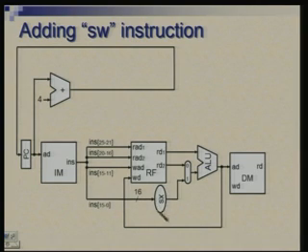So, this is the block which is doing sign extension. It takes 16 bits as input, bit number 0 to 15 of the instruction, and it does sign extension. Okay. So, here it is a 32 bit output. So, wherever I have not labeled things, assume that you have 32 bit output, 32 bit signals. Okay. Each wire is actually carrying 32 bits. Exceptions are here where I have labeled explicitly, or here where I have also indicated that it is 16 bits explicitly.